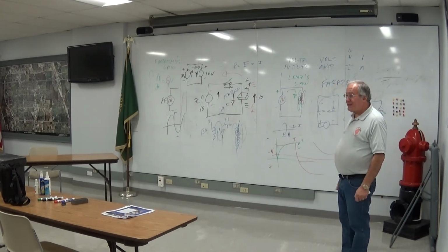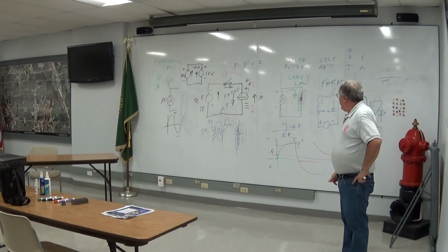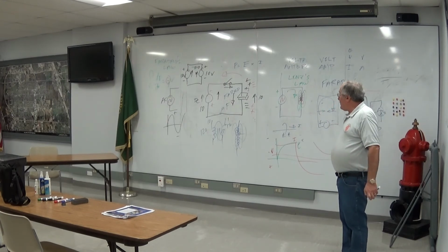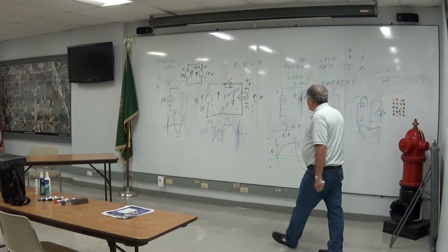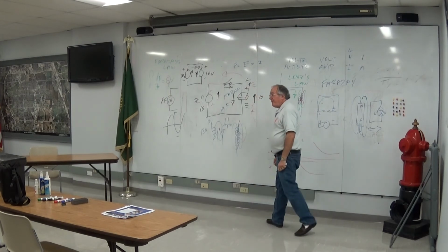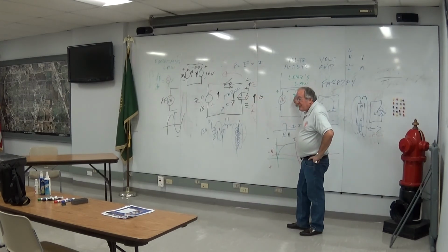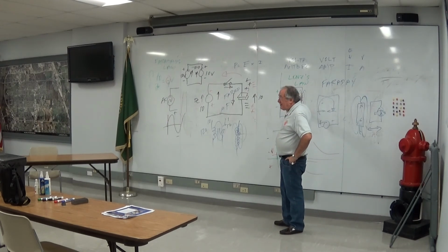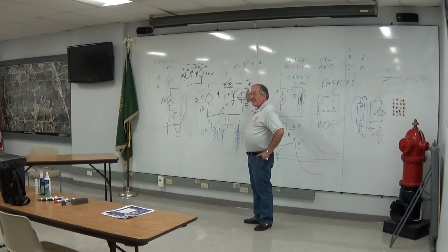And that's the significance of the minus V, and that is why feeding alternating current to an inductor will increase the impedance that it presents to the circuit. Those are equal and opposite characteristics. When this thing alternates faster, it conducts better. When this thing alternates faster, it conducts less. You put direct current through this, it's like it's not there. You put direct current through this, it's like an open circuit.